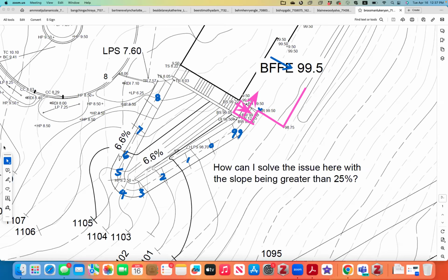So you want this to be a portion of the plaza, and these elevations should be based on that being 99.5. So I'm gonna say this is pretty close to 99.5. That's close to 99.3, for instance, and your 99 would be pretty close to that line. This is a good estimate of where 99 would be. And so that's good. This is good, and this is good, and that is good. But now we need more space over here. Okay, so it did look like you need a little bit longer of a ramp.